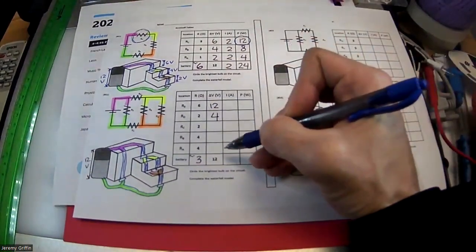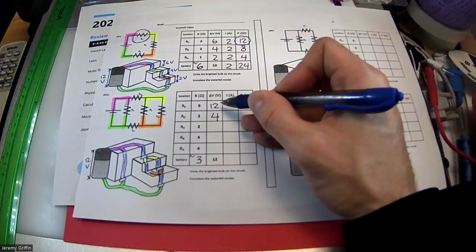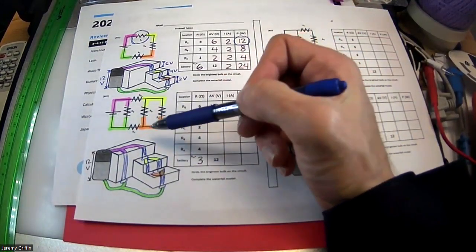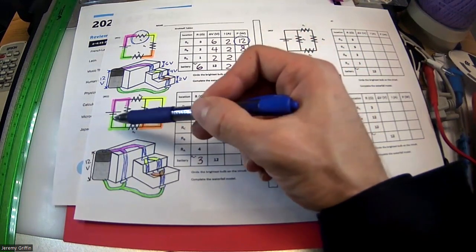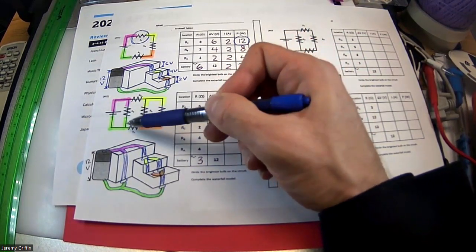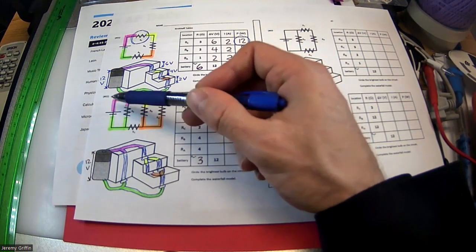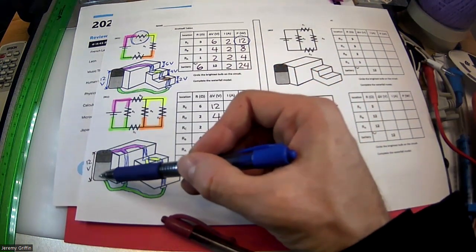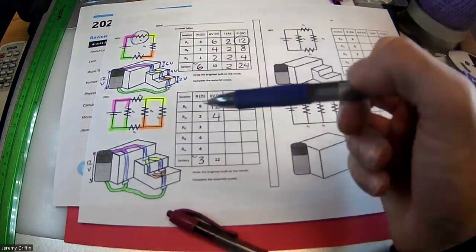So the short answer is however many volts the battery is, just copy paste that number here. And the reason is Kirchhoff's loop rule. Kirchhoff's loop rule says if you identify any loop in a circuit, let's say the leftmost loop, and you go around the loop, the voltage has to sum to 0. So I get pumped up 12 volts, and it goes down 12 volts. Up 12, down 12. In the waterfall model, if you get pumped up 12 meters, you're going to fall down 12 meters.